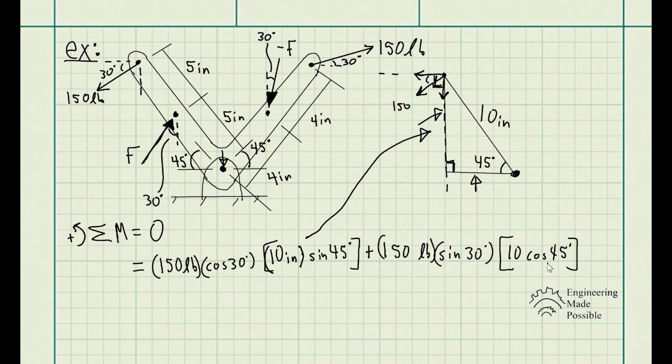Remember, there's still three more forces to go. So let's go ahead. It's the same process. You draw triangles, simplify the problem, and see how you could come up with that distance that's perpendicular to the forces with respect to each of its components. Sometimes you will find problems where, very conveniently, the resultant force is already perpendicular to the distance from which you're trying to solve. It's already part of the dimension. But in this case, that's not the case, and we had to find those perpendicular distances.